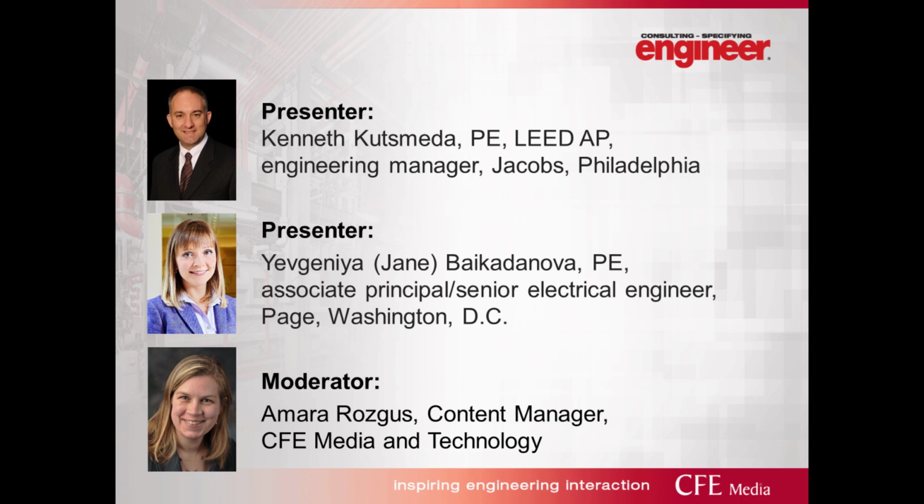So generally, there are different things you can do. Obviously, a generator at medium voltage at 15 kV. If you're running a campus that's higher than that, I had a project where the campus had a 35 kV loop. They had a data center on the campus that was 5 kV with a chiller plant that was 5 kV. They basically got rid of the data center and had this generator plant at 5 kV, which we used.